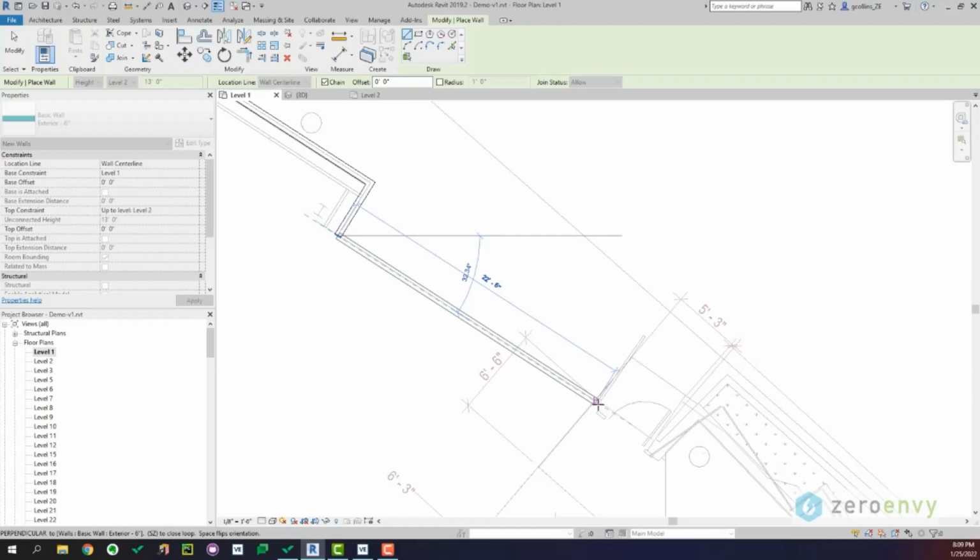Because when you're doing an area takeoff on the PDF, you typically use the interior surface of the wall, right? But the energy model is going to pick the center line and consider that as where the wall is. Let's say you follow the center line and the wall thickness is 6 inches, you will end up having a 3 inch increase on each side, and then eventually you will have a larger floor area for that room. I just wanted to bring up this point, be mindful that depending on what approach you choose, it's going to have an impact on the floor area. So I will just keep going to finish this floor.